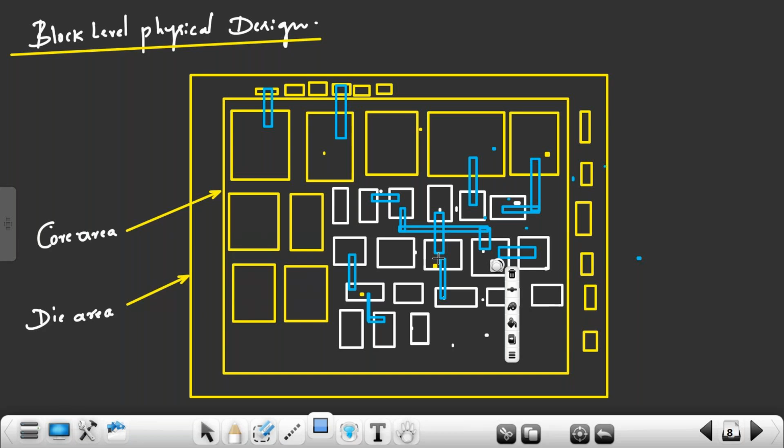A cell and B cell should connect, and C and D should connect. But what is happening? C is also connecting to A. This unnecessary connection is seen in what? Layout, but that connection is not seen in the netlist. Then there is a short present in the what?